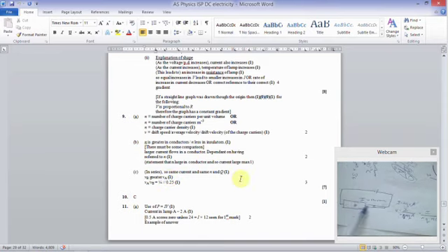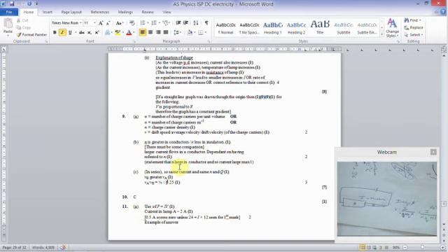So there we go. The same current in A and B, so I've written that over here. I is the same in both of those because it's in series. vB is going to be greater than vA, because the diameter is smaller, so therefore the v can be larger. So vB is greater than vA. If the diameter is doubled, the velocity quarters. So I've got that idea over here: the fact that vB over vA is a quarter. So if the diameter doubles, it quarters. Straightforward as that. You don't need to write it as a ratio, you can write it as a relationship as was stated there. Brilliant.